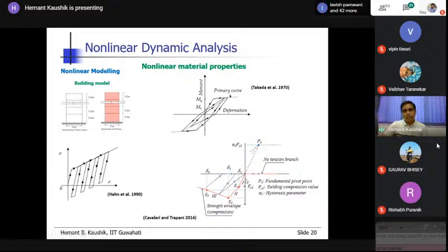So in case of masonry, there is a pivot model. So what we do, we consider a point here which is called the pivot point, and all these values are changed about this point. You can see. So this is a pivot. So this is the stress strain curve or the load deformation curve in compression. So this is the strength envelope. But during earthquake shaking, if from here it has to degrade, then you have to specify how it can go back, what is the slope, then how it reaches here or it goes back here, but this is tension. So it has to go back from here and then again increase in strength, come here.